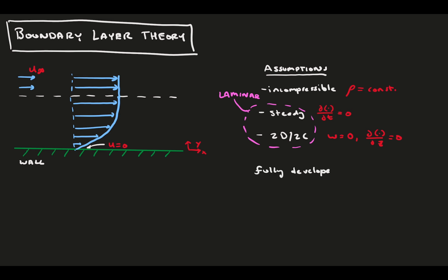At this point, we almost instinctively write fully developed, but for boundary layers and most external flows, this is not the case. These flows develop in the x direction, and we can no longer ignore x gradients in the velocity field. So regrettably, we have to leave this assumption behind because we can't use it. Last, let's assume there are no body forces for now.